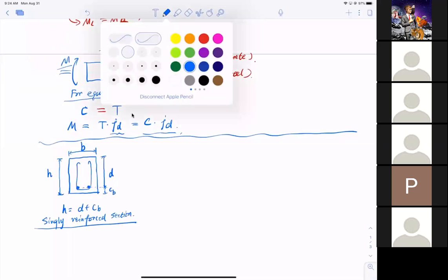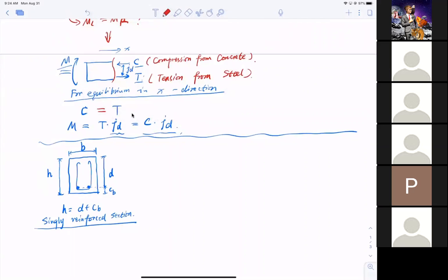I want to see how the stress and strain distribution looks for this section. So first of all, I'm going to assume a neutral axis. I'm going to draw that out like this, and you will also draw it again for this course. If that is the neutral axis, I start out by drawing the strain distribution. You can see that I immediately draw a linear line here in terms of strain, and that comes from a fundamental assumption of bending of a beam. That is,